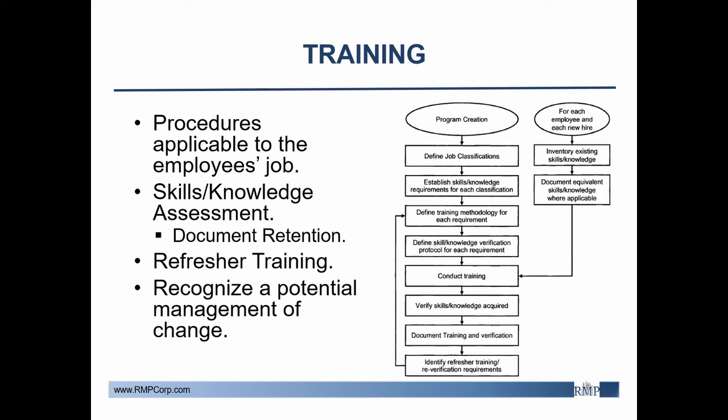The venue, type of training, frequency of training, and competency tests need to be documented. 3, that training and/or qualifications in the general craft and specialty skill that were required to perform their work. However, this does not mean that a company needs to establish a formal apprentice program. And 4, a special subset of general craft skills includes specialty skills that require certification of the skill by an outside agency. This includes welders, API pressure vessel, tank and piping inspectors, non-destructive testing, vibration monitor technicians, and thermography technicians.